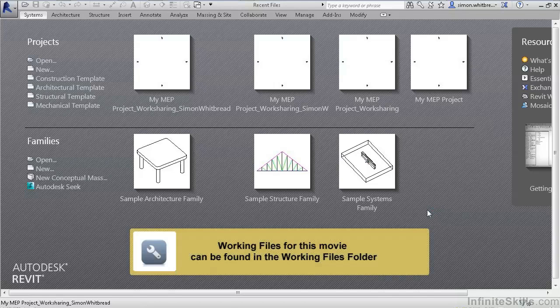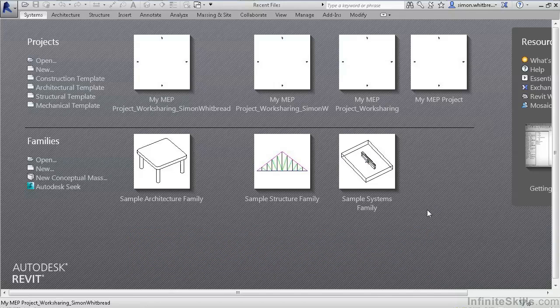We've already discussed the need for using architectural DWGs in place of a Revit file. But why would you do that if the architect was also using Revit? In the early stages of the design, the architect's model can be quite fluid. And if you, as an engineer, are trying to do building analysis, then this fluid model may not be the best answer. So what we can do is create an architectural file based on the architect's 2D drawings. And that's what we're going to do in this exercise.